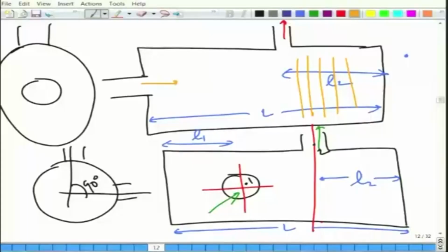In such a case, the inlet can be on the side surface or the outlet can be on the side surface, and it is purely due to logistics. And actually it turns out that sometimes these logistic arrangements are good as far as attenuation is concerned, because we see that the cavities that are formed in the space between the port and the nearest end face act like quarter wave resonators. So, their function is, like I said, similar to the extended inlet and outlet chamber.